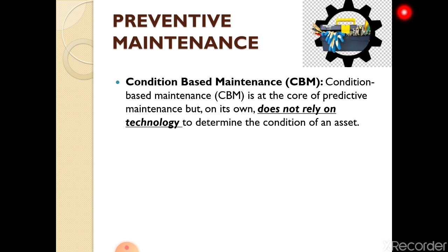So most failure modes are not age related. However, most failure modes do give some sort of warning that they are in the process of occurring or about to occur. If evidence can be found that something is in the early stage of failure, it may be possible to take action to prevent the failure and to avoid the consequences of failure.